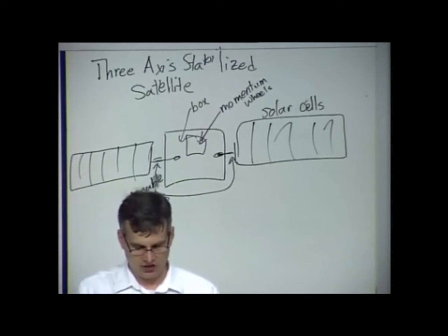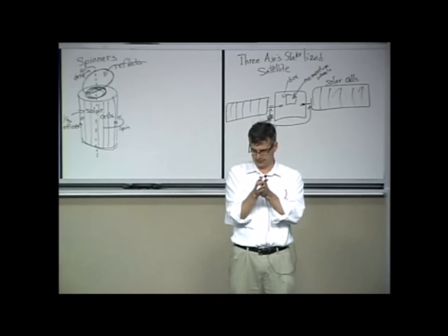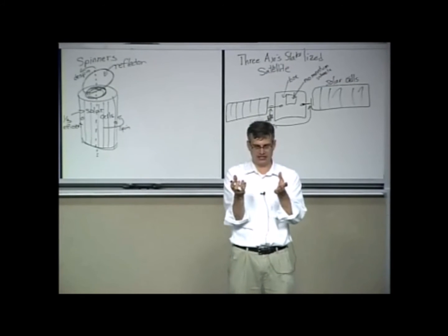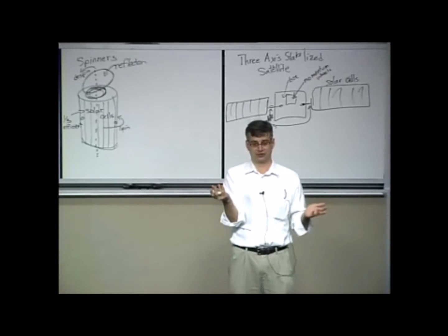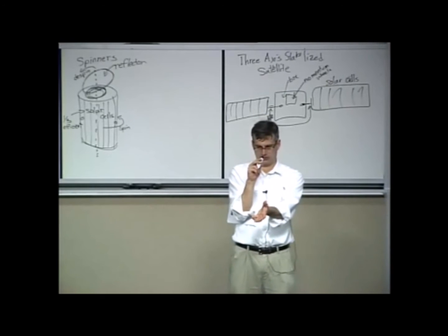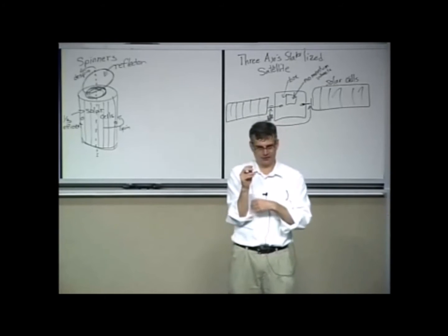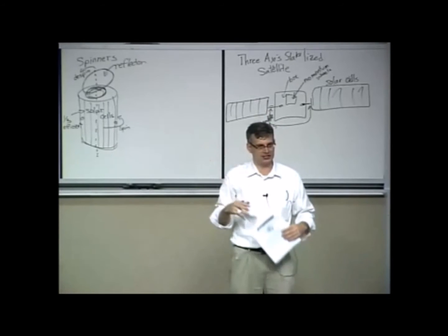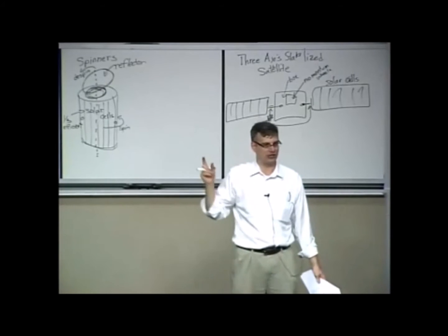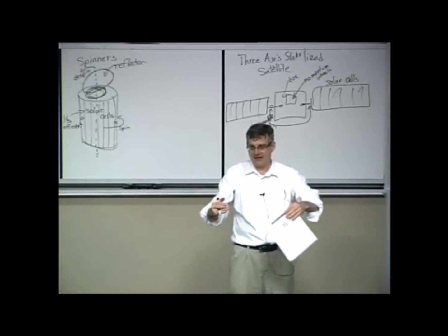Keep in mind that if I were to put this spacecraft pointing towards the Earth, and let's say it was in an equatorial low Earth orbit, and I gave it just enough spin so that its rotation was 1 sidereal day. And so therefore it would be sort of phase-locked with the Earth as well. It would rotate almost as fast as, well, exactly as fast in theory as it would go around the Earth. However, over the course of many orbits, errors would build up, and eventually the thing would be pointing off into space.